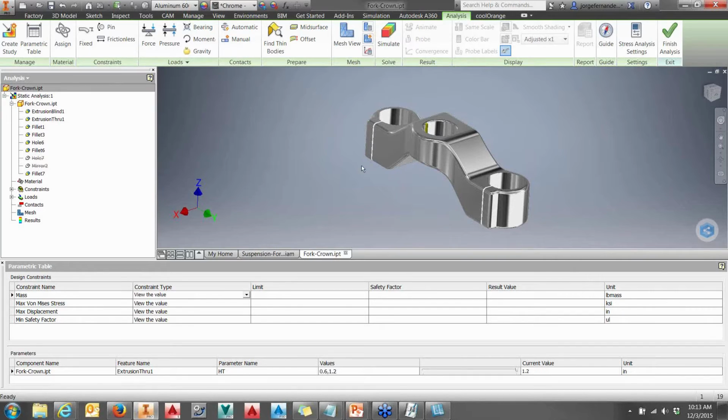One example I've seen before is, let's say there was a part underneath here and they were screwed together. You typically don't want to do an FEA with the bolt in here unless you had a specific analysis of the bolted connection. So you could just say that you want to put a manual contact between this surface and the one below it, and that would add that type of contact instead of having to model a bolt and put it in here.